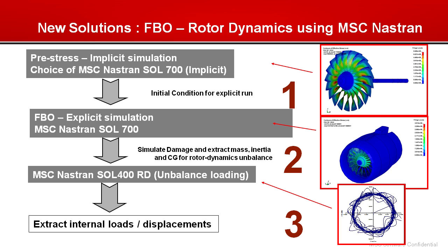A 2 to 4 million element engine model can be very typical in this industry. Whereas a typical rotor dynamics model constructed by airframe manufacturers is less than 50,000 elements and perhaps even much smaller when a super element dynamic reduction is performed to reduce the size of the analysis matrix.